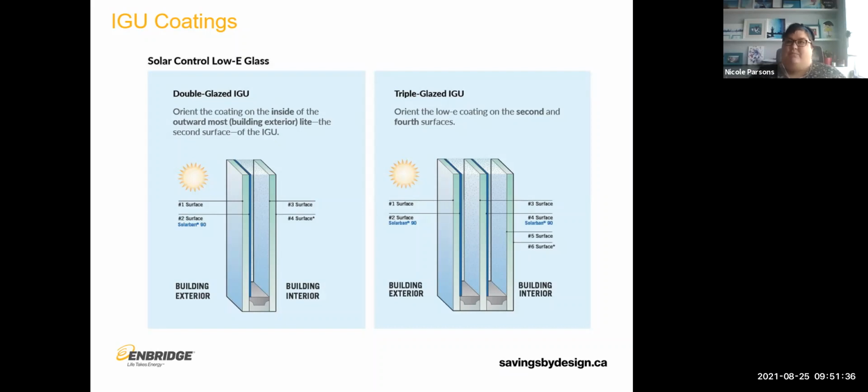So that improves the U value of the assembly. This arrow is backwards, but the heat that would escape through the glass unit is reduced because you have this extra insulating airspace with argon and an extra piece of glass. It also gives you the benefit of being able to apply additional coatings.